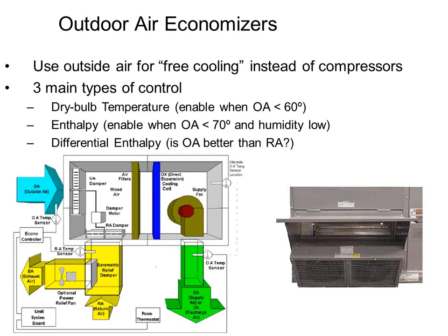So if the unit is bigger, and in my mind bigger means 15 tons and larger, it is worth it for me, even if I have to replace the enthalpy sensor every 5 years, not even calibrate, but just replace it every 5 years. It is worth it for me to do that on the 15-ton unit and buy a new sensor every 5 years, because the energy savings is going to more than make up for that, right? But if I got a 3-ton rooftop unit, it's probably not going to make a lot of sense. The savings won't be that much more because the energy costs aren't that much to begin with, so buying a new $200, $300, $400 sensor every few years is not going to be a great scenario for me, right?